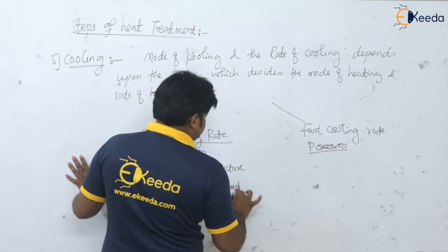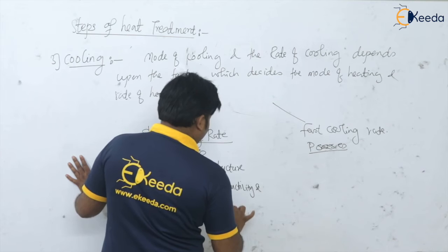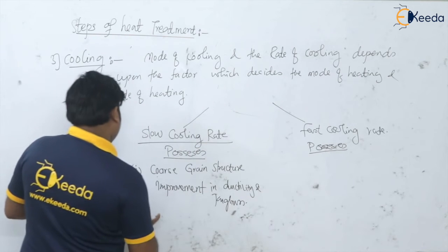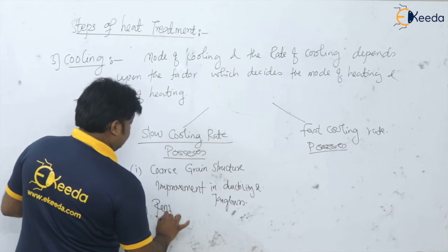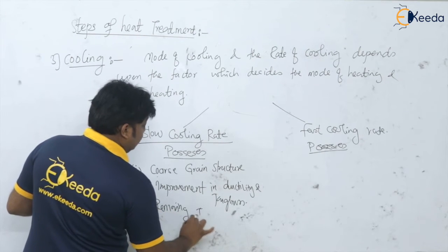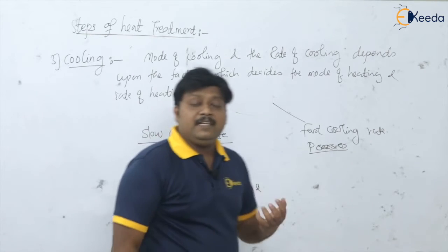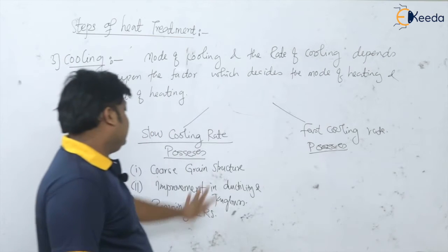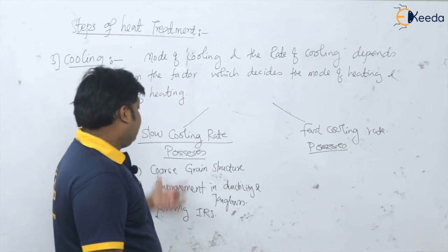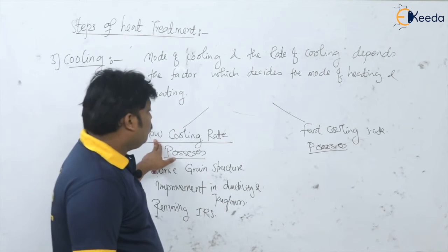Then we can have an improvement in ductility and toughness. And the third thing, we are removing the internal residual stresses. So when we cool with very slow cooling rates, we get these advantages.